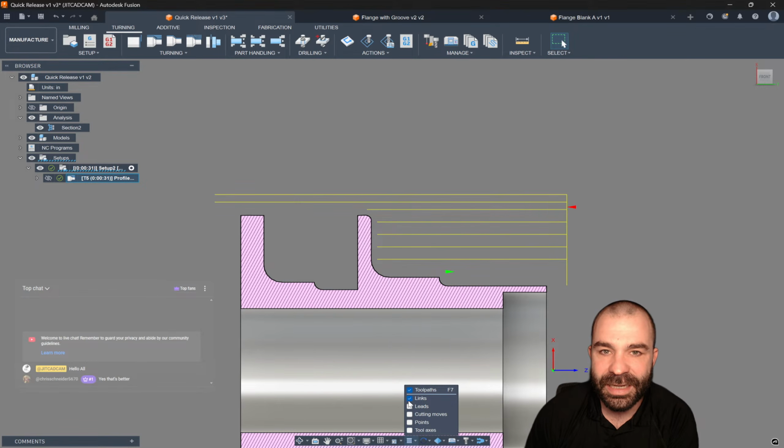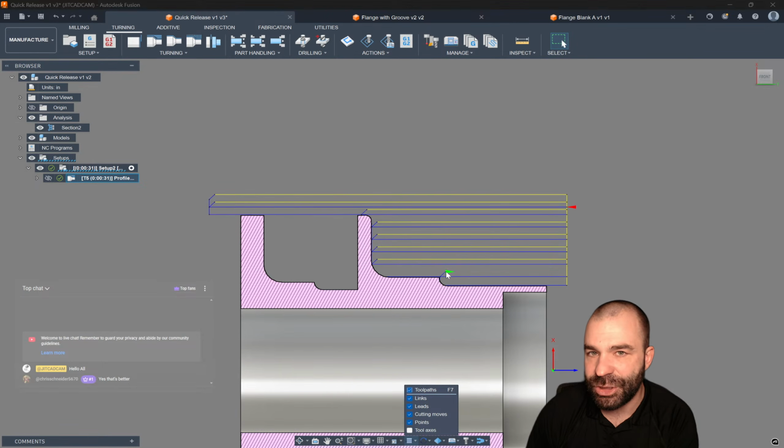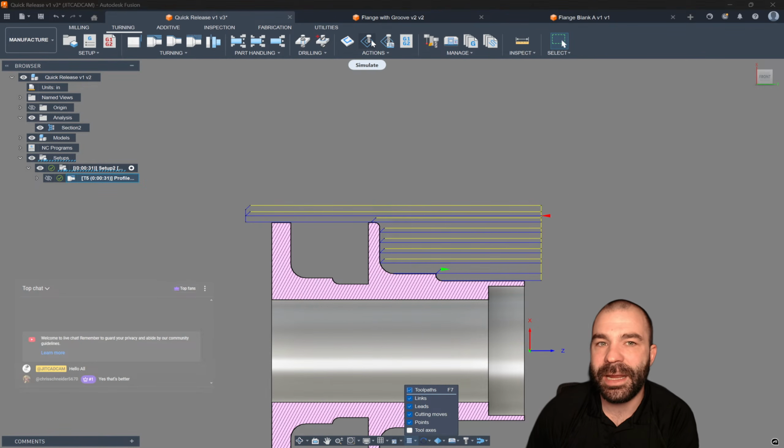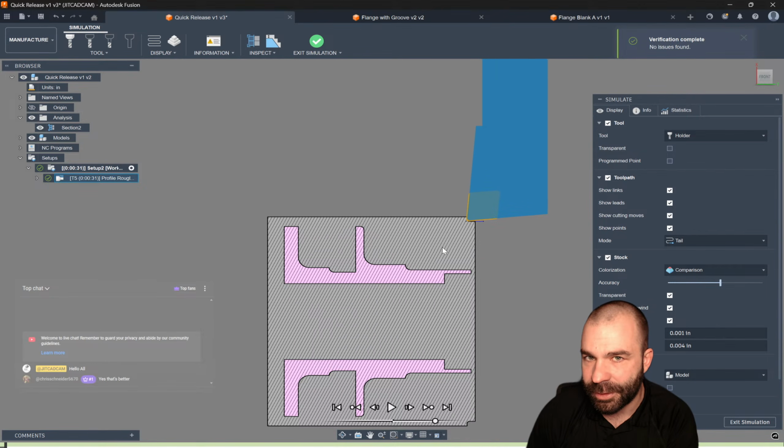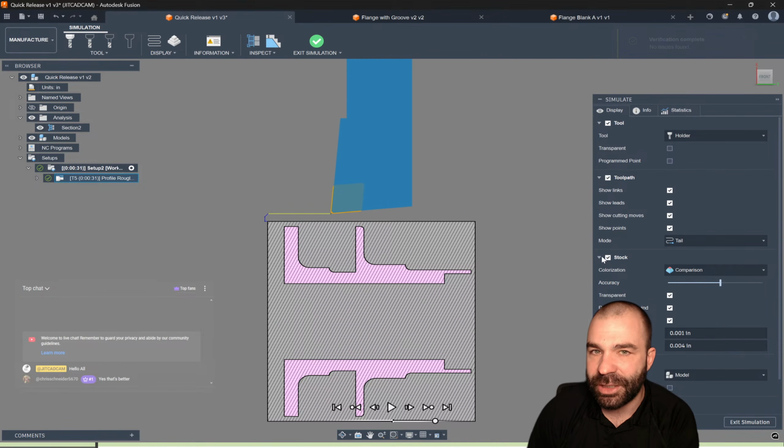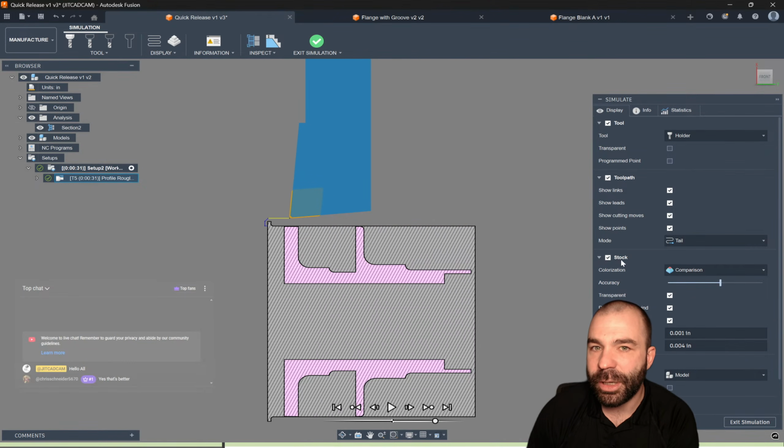As you guys have seen, I've turned everything on to first and last point. Again, this could be dangerous depending on your machine where we're going to stop that cut. But from this point, we could go ahead and simulate this tool. As you guys are seeing, my tool is right on top of my part and immediately starting to make my cut. So by making that adjustment, we are getting really dangerously close to my part.